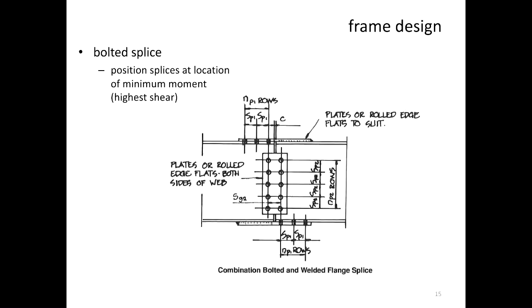And what happens to the bending moment? Remember that? In materials and structures. You must have seen that. So bolted splices always should be placed where you have minimum bending moment, because if you have a bolted splice, most of the time they have to be designed to only transfer shear force across the joint rather than bending.